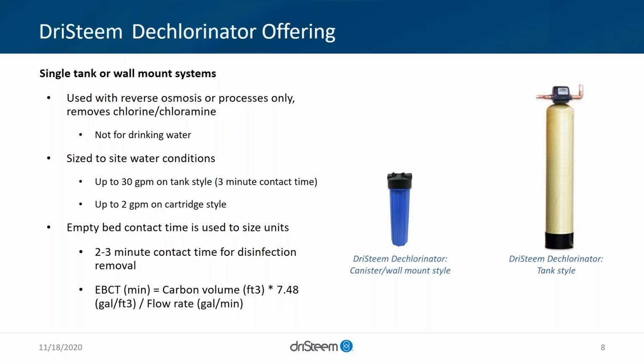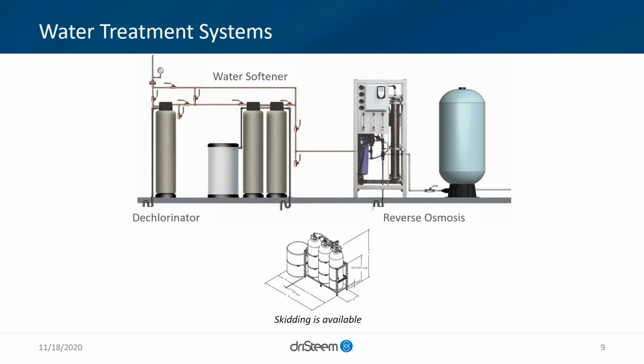So the cartridge style is great for low flow rates. The thing we're really looking for is contact time. I didn't put this exact info in the presentation, but I believe Pentair water talks about 5 grams of activated carbon equaling 32,000 square feet of surface area. So this carbon, as you break it down, becomes more porous. But along with that, we do need contact time to effectively remove and have that reaction occur. And then same with the inside of a tank style, it's granular activated carbon. I have a picture of that on the next slide. Actually, excuse me, 2 slides from now.